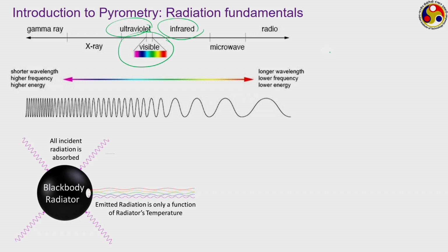Radiation is dependent on temperature, radiation emitting from a surface is dependent on the direction, and also it depends on the wavelength. So, accordingly we use the terms spectral and directional. Spectral refers to the dependence on wavelength, whereas directional dependence indicates the dependence on the direction. If we are working in a spherical coordinate system, then it depends on the value of theta, the zenith angle, and phi, the azimuthal angle.